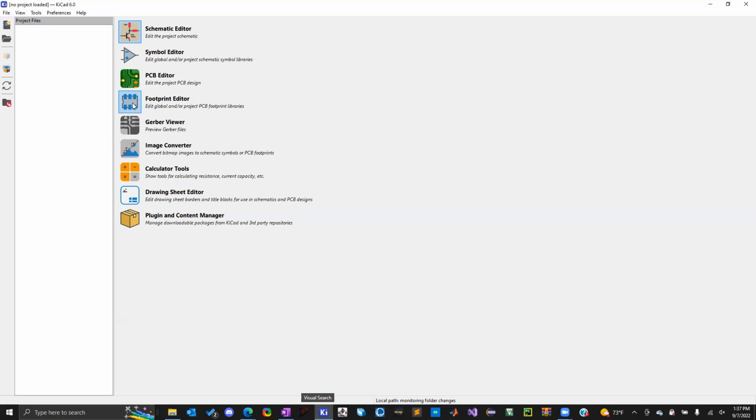It's common practice when you're naming your footprints to put in the name of the footprint the size of the chip and the pitch between the pins, because when you're picking out your components and looking at their data sheets, they'll tell you the package type, usually, ideally.